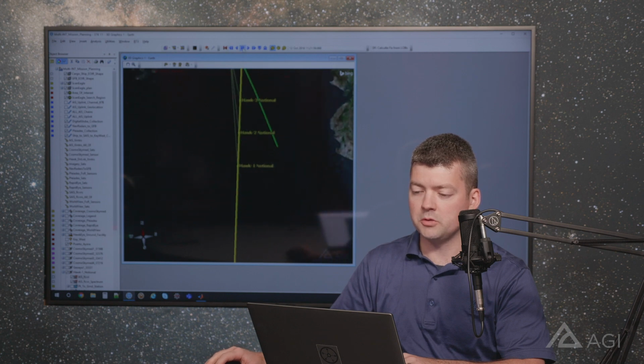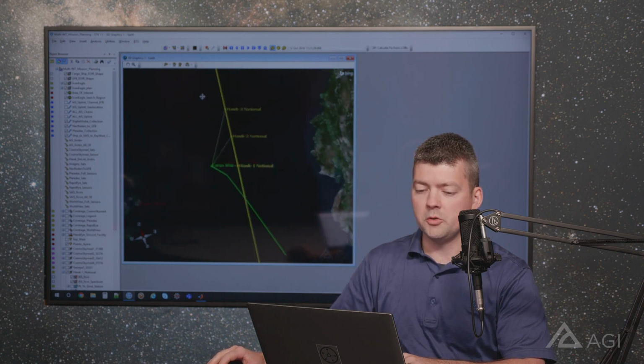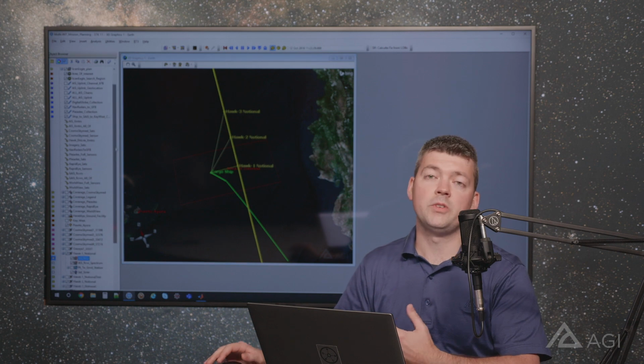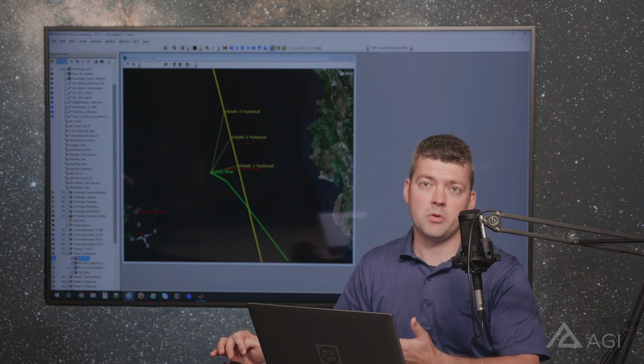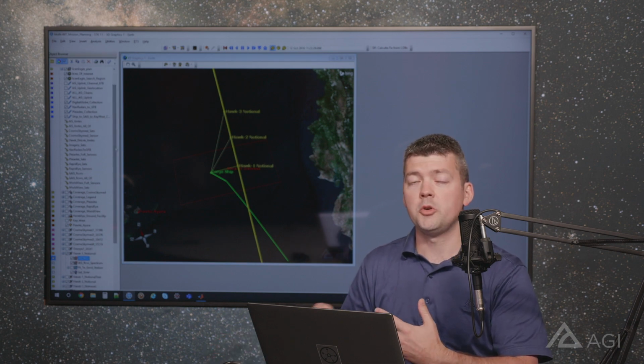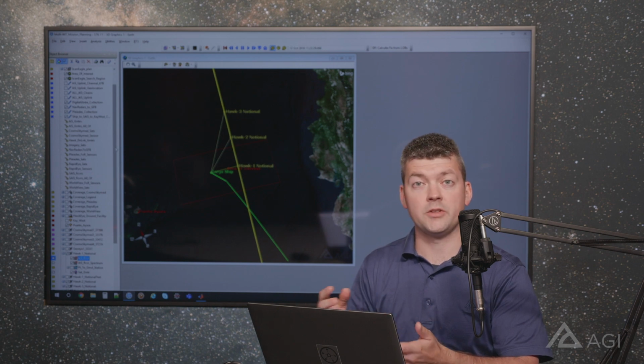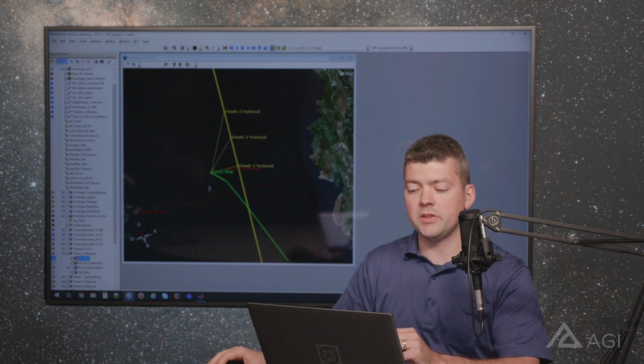So the next question is, how quickly can I get some satellite imagery in this area of interest to better assess the situation? All right, so what we're going to do next is we're actually going to use STK's coverage module, there we are, to look at when some various imagery satellite constellations come overhead. So essentially the question is, who is going to be able to search this area the soonest? So we're not interested in just a single point, we're interested in area coverage.